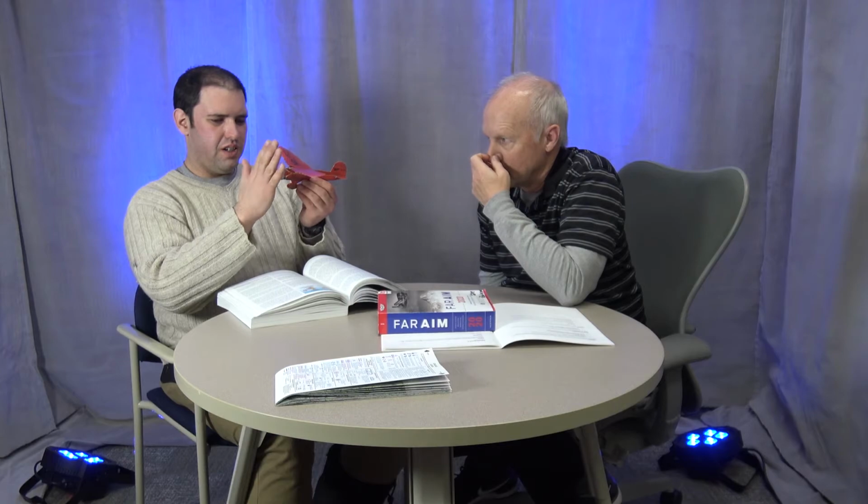But because of the gyroscopic effect, rather than simply wanting to push the tail back down, that force manifests 90 degrees off, and that manifests on the left side, pushing the left side back, and that makes, as we pitch the nose down, the airplane want to turn left. And that's why, as we take off, when we raise the tail on the Chief, you'll notice you'll have to add more right rudder as the tail comes up, and that's part of the reason why.